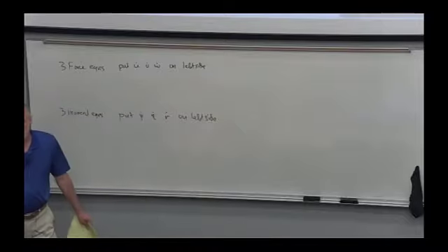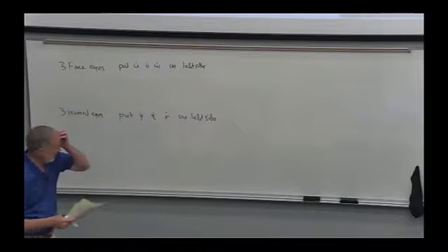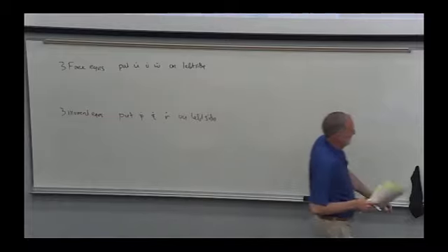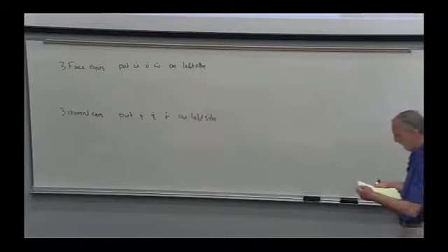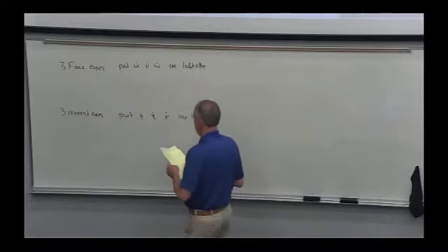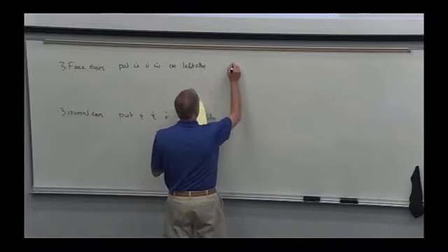You just shove stuff on the right, and then like here we divide by IY to get Q dot all by itself. Here we got a P dot and an R dot in both the rolling moment and the yawing moment equation, so you have to solve two equations simultaneously to get P dot and R dot. But that's just algebra. And so what you end up with is